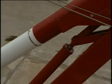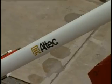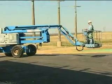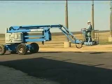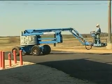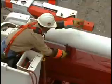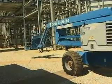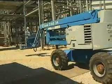The first step is to ensure that the lift is lowered and safely resting on its support. If the lift is not on its supports, damage may occur to the lift as well as create a tipping risk while being transported. Always secure the lift to its supports while transporting it. This keeps the lift stable and minimizes the risk of unwanted movement.